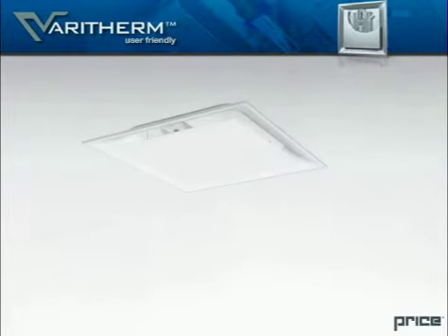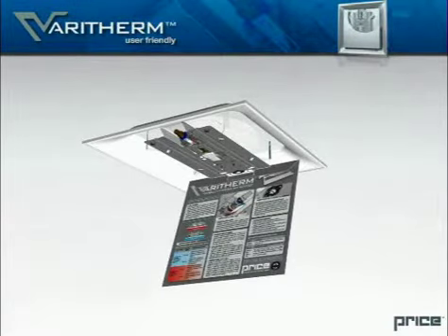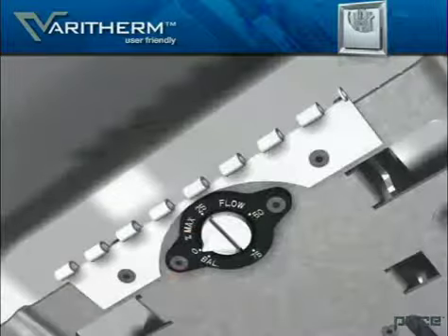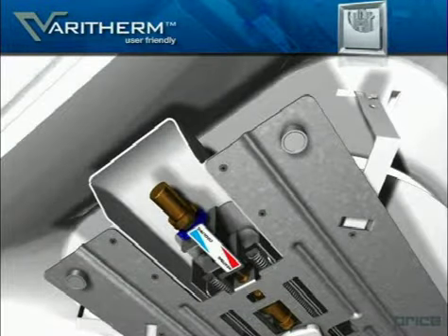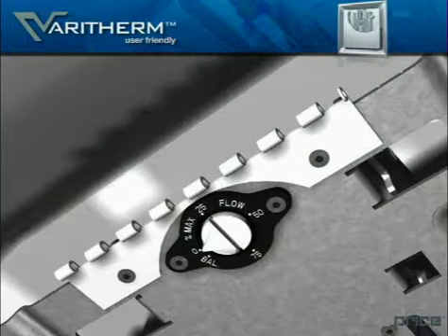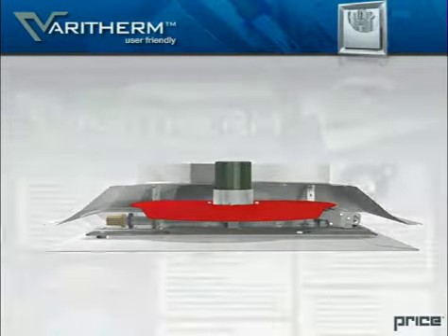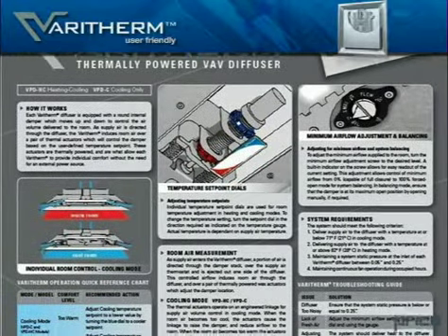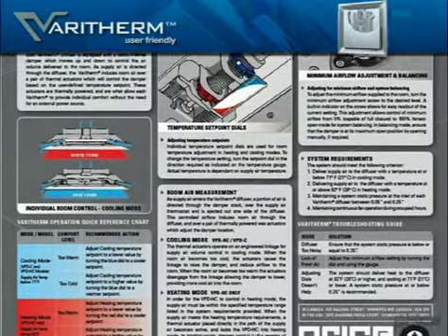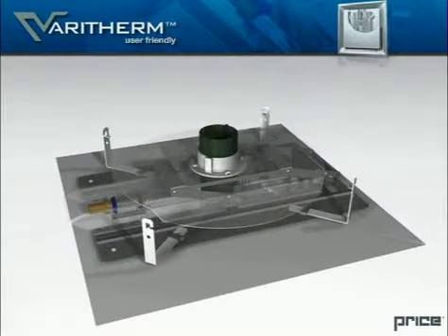User-friendly. The Varitherm is easy to install and use. Simply opening the plaque allows the user to make control adjustments. The plaque pivots securely on a solid hinge and is held closed by a set of powerful magnets. Easy-to-read gauges let you know what your settings are. Temperature is adjusted with the spin of a dial, and the minimum airflow setting is adjusted with the turn of a screw. The unit is also equipped with a forced open mode to assist in system balancing. All guidelines are simple and easy to follow and are written in a clear format on each unit. Optional security fasteners mechanically lock the core into the back pan, where required by code.